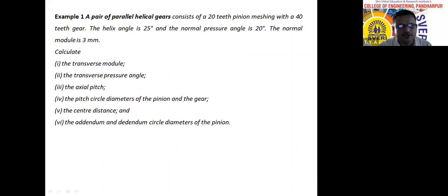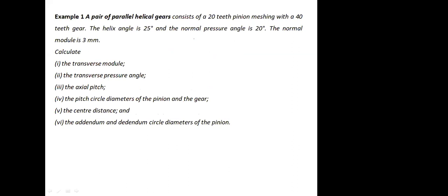Therefore, write down this equation. Face width: write down this equation only. B is equal to pi Mn upon sin psi. Now, based upon this, we will solve the problem. Whatever equations we have seen, therefore write down the problem.